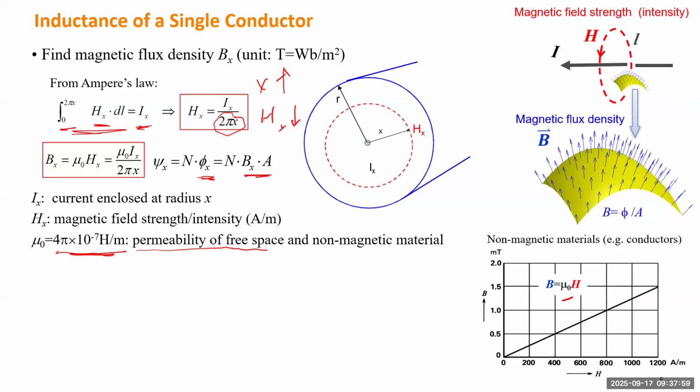For the entire conductor, that area is A, but for a smaller piece of conductor, you can calculate that part of A. N here is just the number of turns. If you have a wire, maybe there are many turns of the wire coupled with the current, and you just count how many turns. It's similar to the transformer. On each leg, you have many turns of wire, and N1 by N2 will be equal to V1 by V2, right? That's the formula we use.